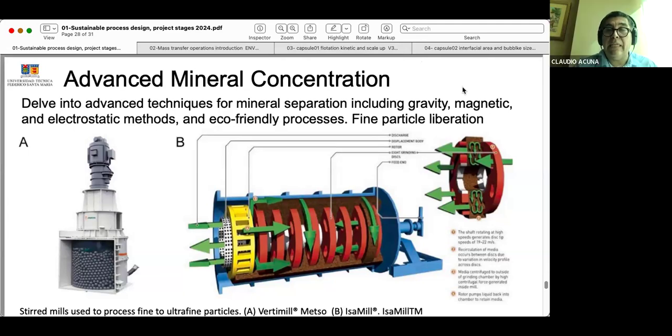Okay, you have a recirculated, it depends, but usually you have reverse grinding. Reverse grinding means first you classify and then grinding, and that goes to cleaner and then scavenger. But also in the final tailings, we have losses of the valuable elements, and in some cases you can reprocess the tailings. So the next question is, why are we losing valuable materials in the final tails?